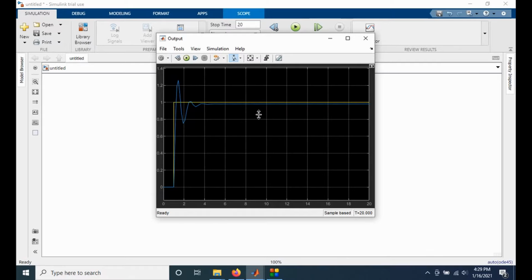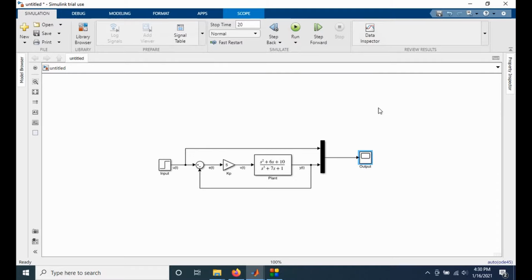Now it becomes a lot more apparent that we have a steady state error, so the proportional control is not sufficient, and we need to start looking into the I and the D of the PID controller. The integral portion of the PID controller is perfect for systems that have a steady state error. This is very common for systems that have a lot of friction, where the purely proportional gain is not sufficient to drive the error to 0, but gets stuck somewhere just shy of 0.